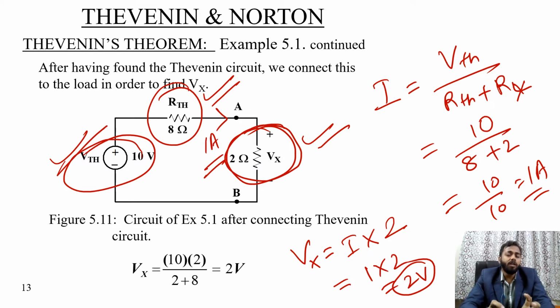This is the maximum power transfer theorem where the load resistance is variable, and when the load resistance is equal to the source resistance, only then the maximum power can be transmitted from source side to load side, and we can find out the voltage drop across the load in a better way. That is equal to what? V square over R, the power in the load, that is the maximum power, in that case when the source resistance is equal to load resistance. We will discuss everything: Norton theorem, Thevenin's theorem, maximum power transfer theorem, superposition theorem, in the subsequent lecture.